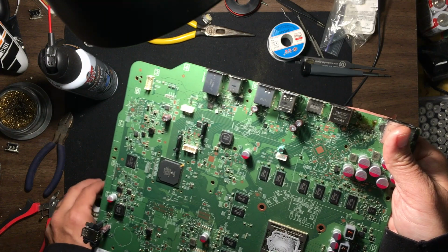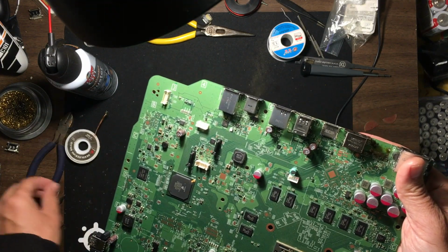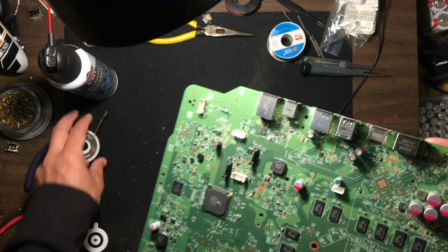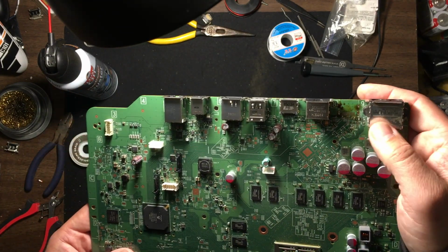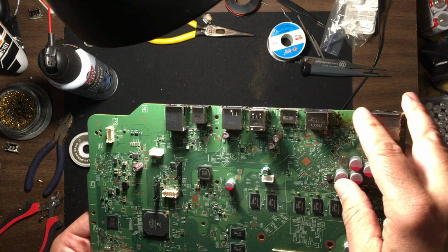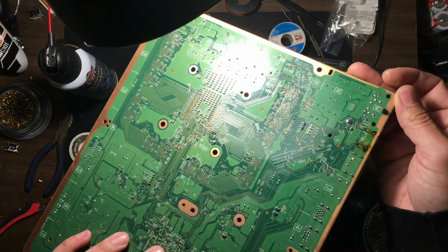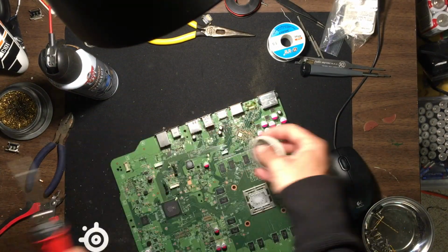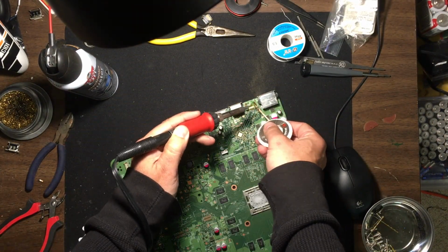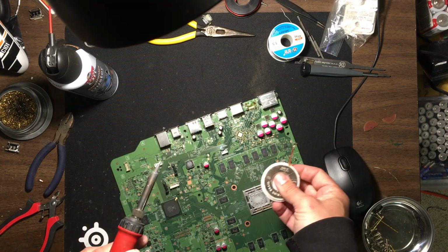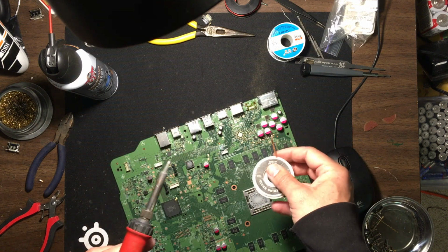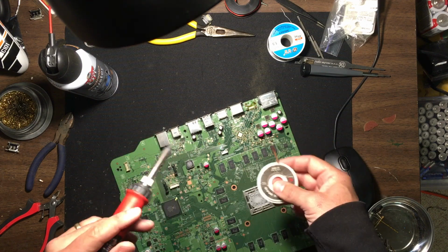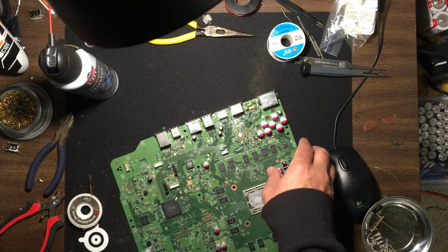The flux will cause the solder to melt easier, and it'll adhere to the desoldering braid easier. And I did the front side, put flux on the front side, and I did the back side, put more flux, and went back and forth until eventually, basically, put this down, applied the heat, rolled it, and pulled it off, and it would take a lot of the solder away. And if it's not working for you and you're leaving it for 5 to 10 seconds, it's still not coming off, add more flux and do it again, and you'll eventually get there.